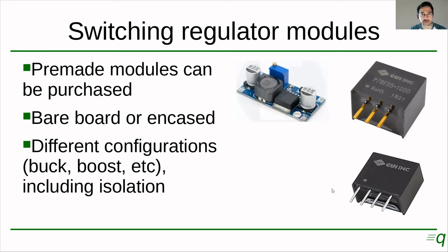Okay. Because of all of these considerations, switching regulators are sometimes not very easy to design correctly. But fortunately, there are several companies that make pre-made modules that you can use, right? So the modules could come like a bare board like this one, right? If you have a look, you have here the controller with the 5 terminals. This is probably your input capacitor. This is your output capacitor. This is your inductor. And right here, this little black thing looks like your diode. Okay, this is a potentiometer to adjust the output voltage, right? Because this is most likely an adjustable one.